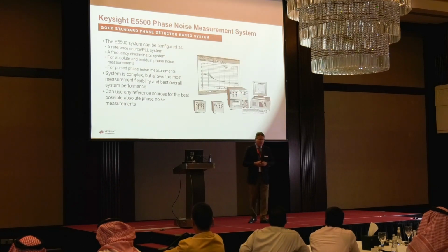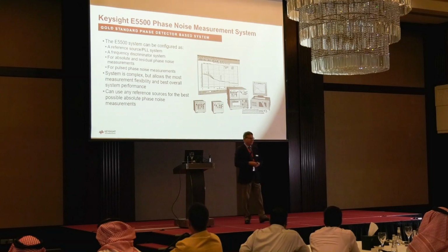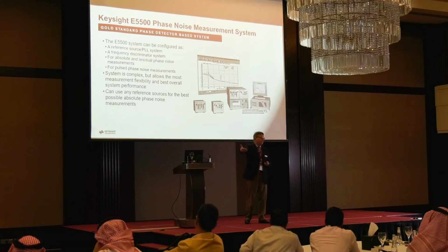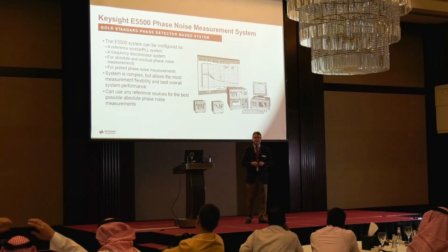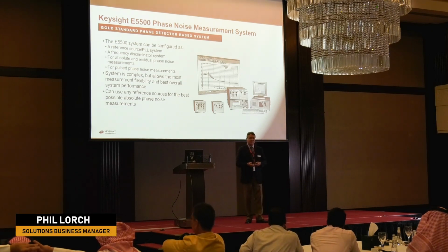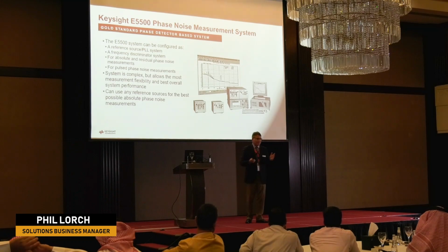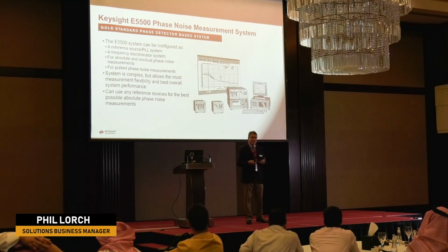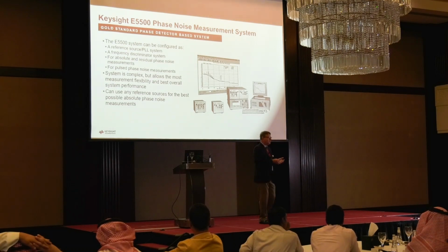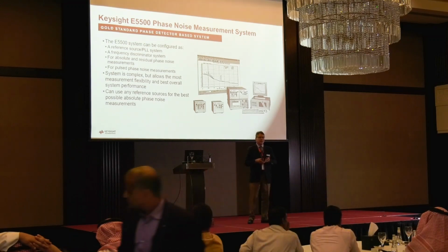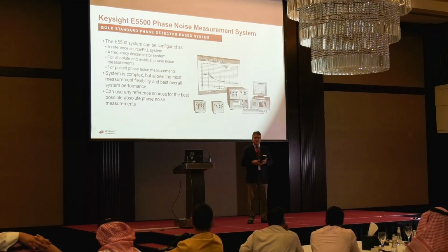We also have a more complex high-performance system, which comes in the form of modules or different components. The E5500 actually uses external reference generators. Typically, it's a PSG with the best phase noise option, and it has a single channel only, so it doesn't do the cross-correlation, but it can do very complex measurements of pulsed RF devices. It can measure both absolute and residual, covering both of those measurement applications.